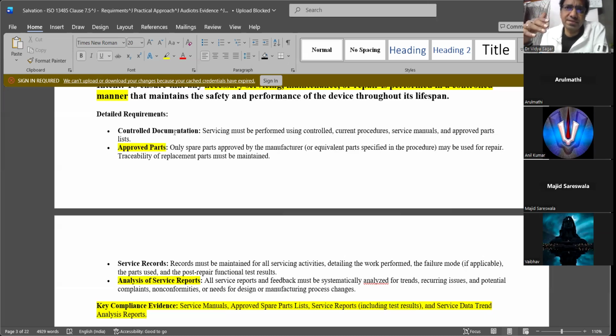And this preventive maintenance has to be done by skilled, trained people. Machinery maintenance is very different from how the shop floor people work. You should have approved spares, and this is very difficult. You cannot buy a machine from one vendor and keep a spare from another vendor until they exactly match and somebody approves it. Changing spare parts from machine to machine will create a lot of problems.